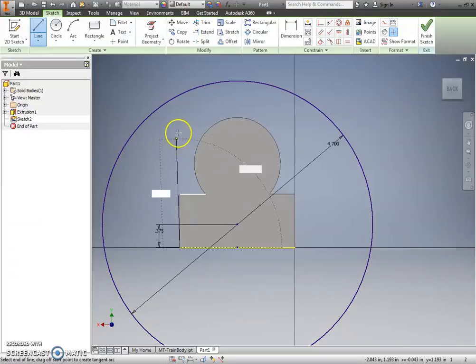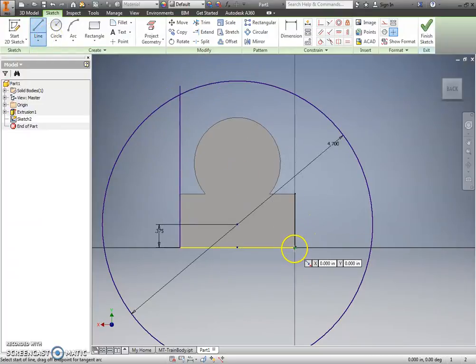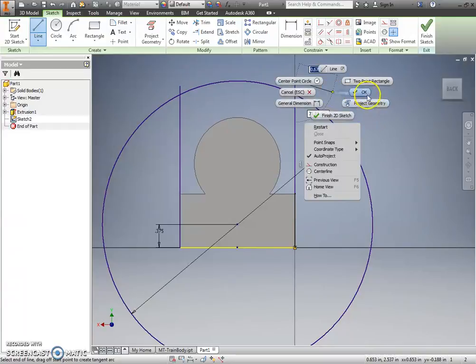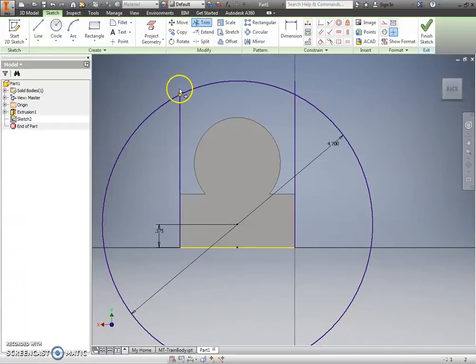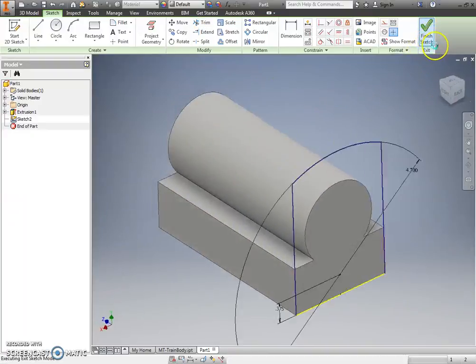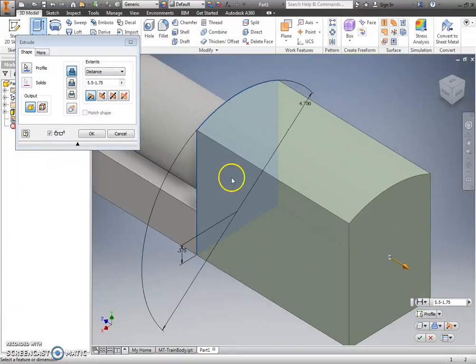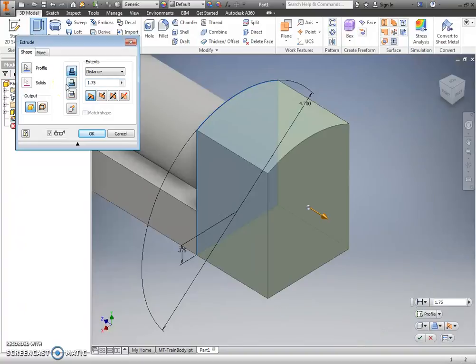But that yellow line should now be a part of my sketch. So if I draw a new line, perfectly vertical, off of each side of it, I can now come in here, trim all this out, and hopefully it'll let us extrude. I might have to draw that line off the bottom, but nope, I was right. And up here, I'm just going to subtract the 5.5 or delete the 5.5 because that cab portion was 1.75.